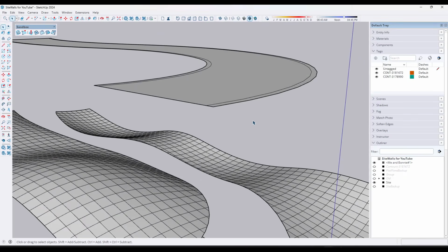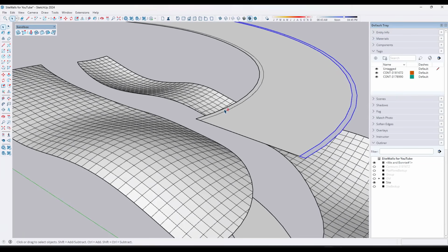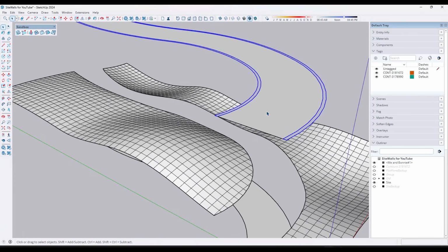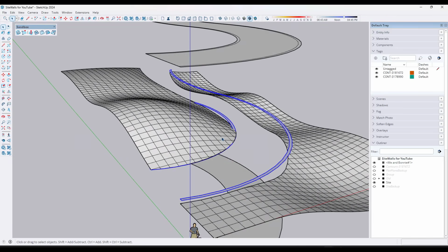And remember, this is 100% flat. So what I can do is double click, shift double click, and I'm just going to make a copy of these using the move tool. So tap the control key with the move tool active. I'm going to move this down in order to create my wall profile in here like this. And so now I've got these two walls in here and I can do whatever I need to with them. So in this situation, I'm going to push pull this wall down right here.